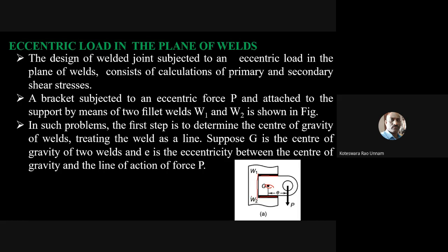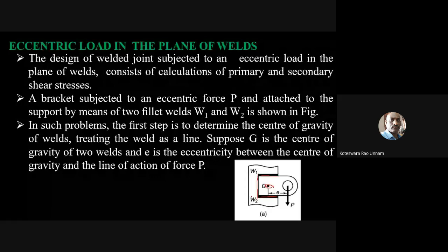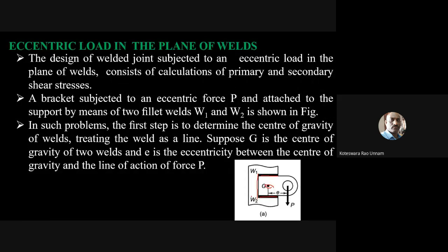So from this, in the data book, for the given weld configuration, you have formulas for X bar as well as Y bar. So center of gravity is denoted by its X and Y coordinates. X coordinate is denoted by X bar and Y coordinate is denoted by Y bar. So only thing is, you need to compute Y bar and X bar. For that, what is required is, you need to know how to use the data book or how to identify the suitable formula for calculating the center of gravity.